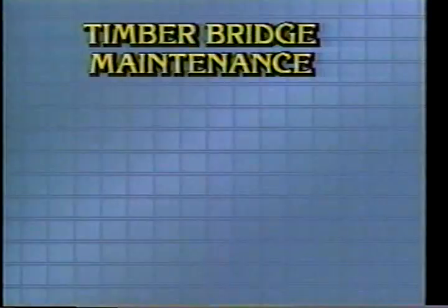I think one of the most important factors in assuring long life for timber bridges is an effective inspection and maintenance program. If we have thorough, periodically scheduled inspections by qualified inspectors, this is the key to an effective maintenance program, and we can significantly prolong the useful life of timber highway bridges.